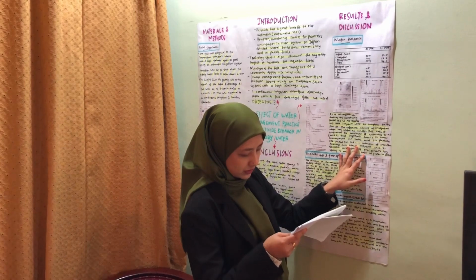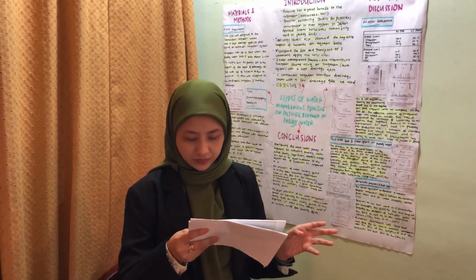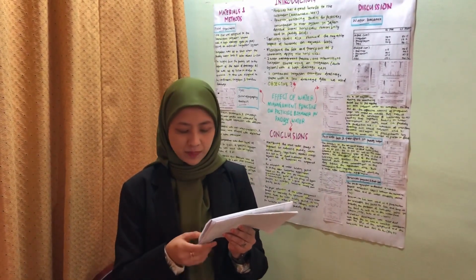This result confirms the conclusion of Watanabe that important factors in water management for saving water use in paddy rice production are, first, reduction of overflow drainage from excess irrigation, and second, efficient utilization of precipitation by storing as much rainwater as possible in the field.